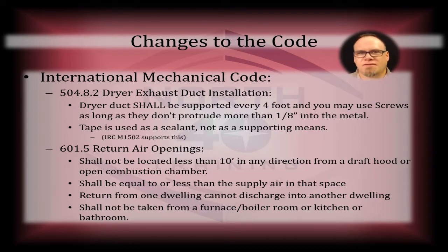A lot of places in life, it's easier to ask for forgiveness, right? You just do it, and then later on you say, you know what? I shouldn't have done that. I'm sorry. That's expensive in the HVACR game because the inspector is going to have the same view before you do it as he does after you do it. The only difference is you spent money not asking. So even though he would have told you no if you'd have asked in the first place, you didn't ask. He's still going to tell you no. You're still going to have to change it and fit what the code interpretation is. So my recommendation is to ask in advance. That's oftentimes going to be your best case scenario.